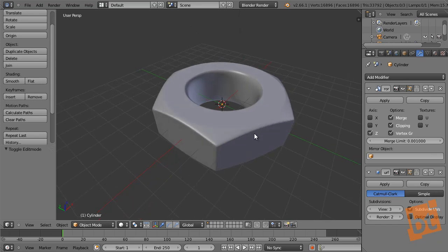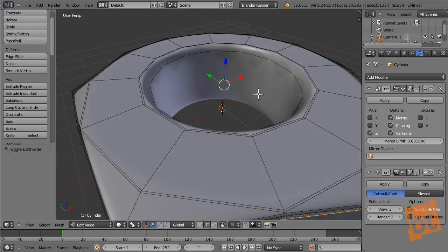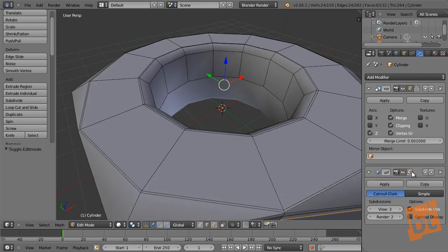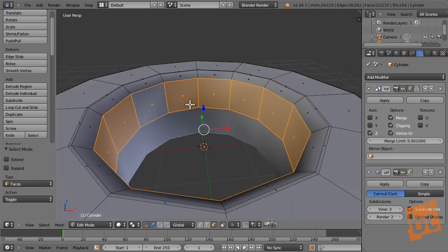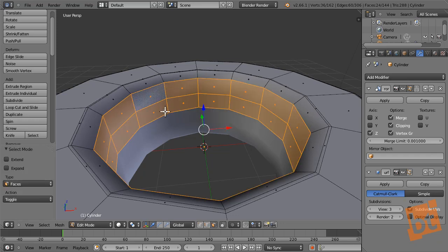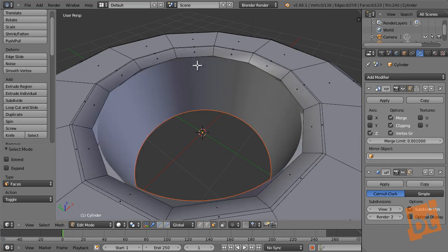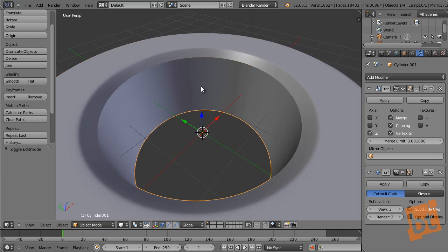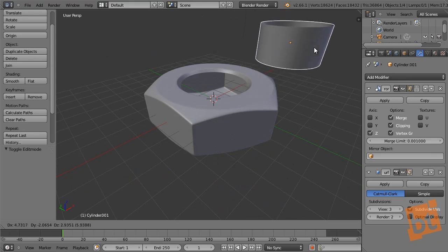Now we need to go to the screw, and later we add the screw to this model, and later we can even define it a little more in the inside part and all that. So what I want to do is to just deactivate here in the viewport in the edit mode the subsurf modifier. I'm going to pick this. Okay, I'm going to divide these ones, and later you will see what this is for. I select these two loops here with Alt and right click, press P, and separate this selection. So now this object is a different one, which is the one I'm going to use as a reference for creating the screw.